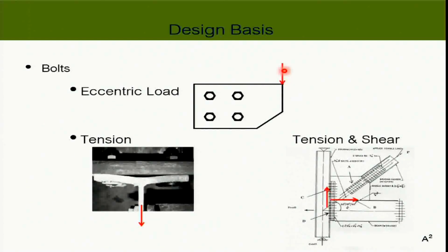If you don't have the load here, the load will travel here, but instead, you need to apply another force to maintain the equilibrium, and therefore a couple is turned into some kind of a moment or torsion. So yes, apparently if the load is there, it means that your bolt group will experience the load itself and extra torsion at the same time. That is why its capacity is reduced. Okay?